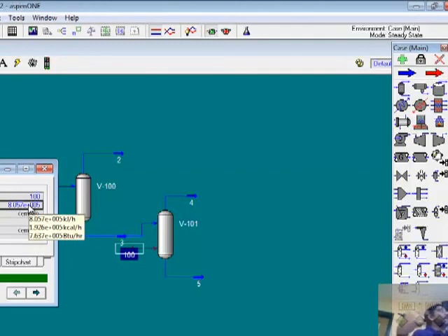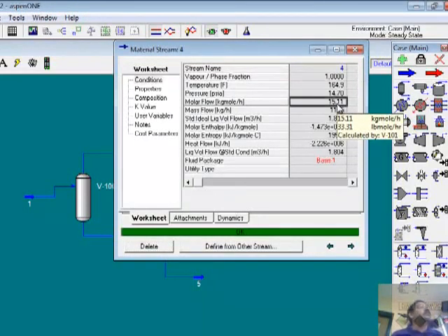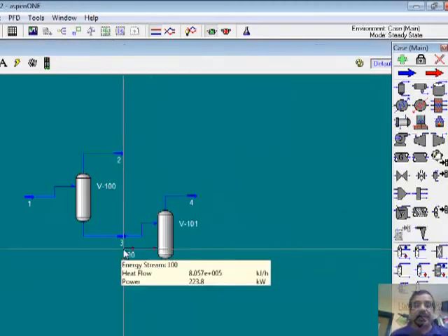This is the iteration that was happening. Remember the last number we had there? About 20,000. But right now it has 8 times 10 to the 5. The adjust block was trying to get to that number, and in those 50 or 60 iterations, it has come there. Now, you may want to ask, at this stage, what is the vapor fraction? From about 0.1 kilomole per hour, it has gone to about 15. If I had pressed that button a few more times, if I had the patience, I would have gotten to the answer. But we have another way of getting at that number,